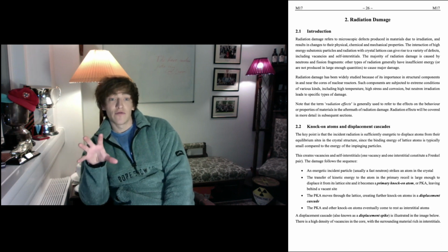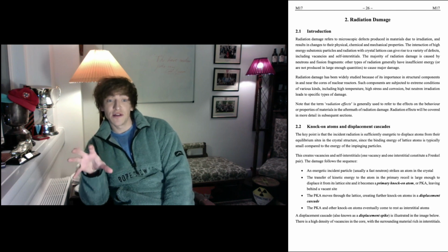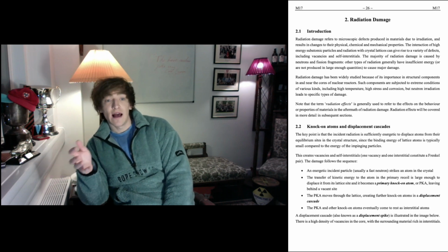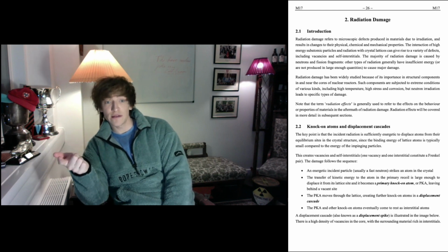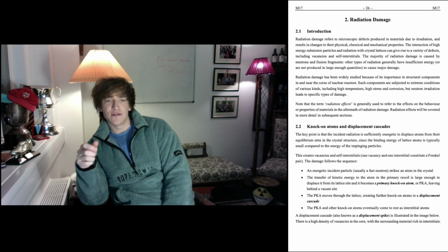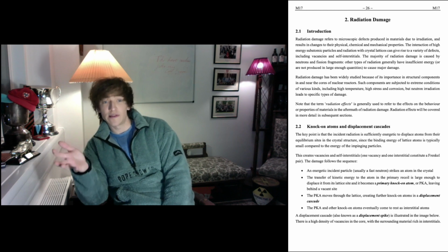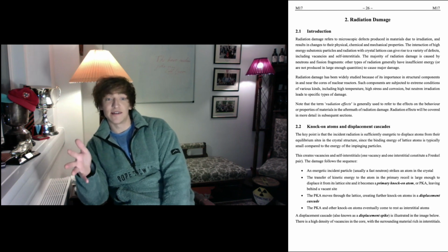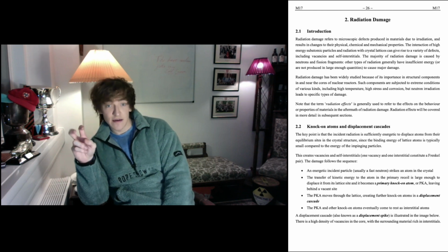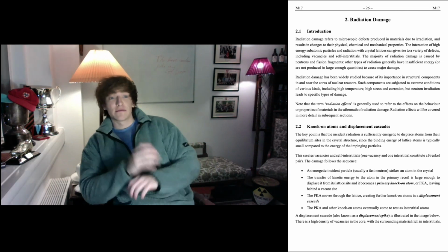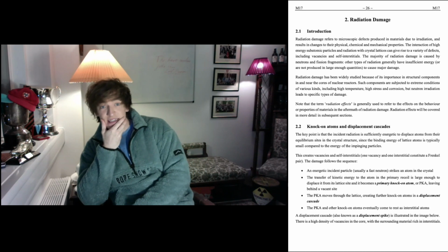But today, we're going to look at radiation damage, and I'll give you a general introduction, the billiard ball-like destruction that particle collisions can have in materials, which we call displacement cascades, how such radiation damage can lead to the formation of dislocation loops, cavities, and voids, and how such damage leads to, for example, mechanical property changes, amongst others. And this will equip us with the knowledge necessary to see how the radiation effects described in the preceding lectures might occur. And with that, let's begin with the basics of radiation damage.